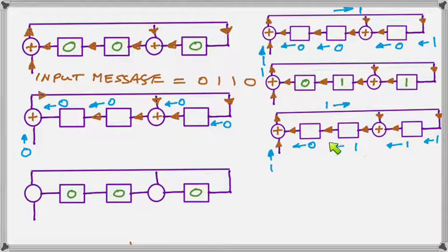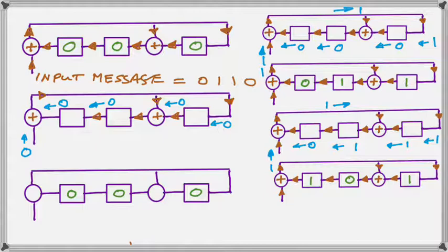So as this 1 comes out, a 0 will move in here, and this 1 will move into here, and the 0 will have already combined with the 1 to produce. So it's a circle, basically, a cyclic operation, and the next state will be 101. Make sure you agree with this.